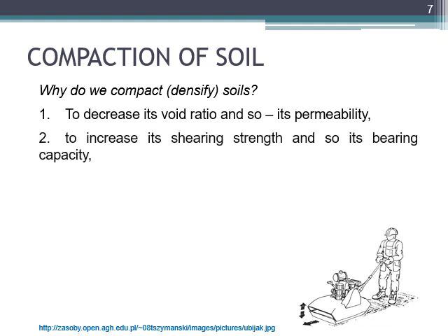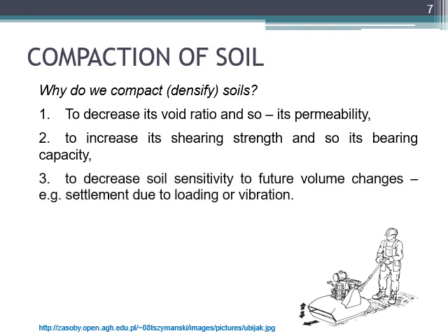Secondly, to increase its shearing strength, and so its bearing capacity. And also to decrease the soil sensitivity to future volume changes. So, for instance, the settlement due to loading and vibration.